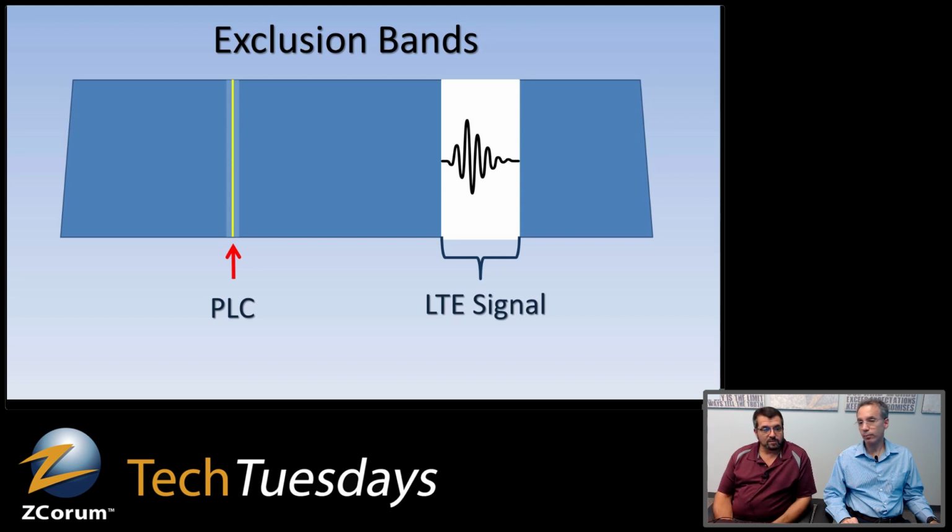It'll be toast. So again, OFDM allows you to have these exclusion bands, and here's an example where you might have LTE interference, and you can actually turn off the subcarriers in that area, and that way you don't need to worry about that interference.